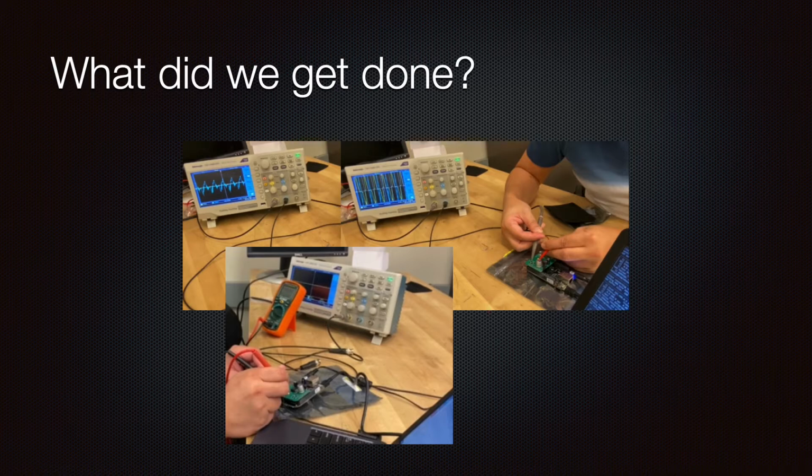During the tests on our last slide, our PCB wasn't on top of our SBC because after setting up our SBC, we learned that we have a software issue. Our outputs from the SBC were stuck at a low and high, so we weren't able to capture the square wave output we were expecting. Pictured here are our first attempts to dial in the oscilloscope.